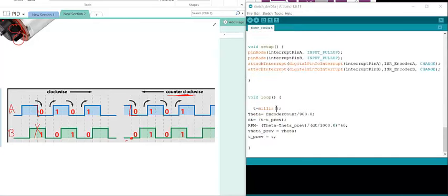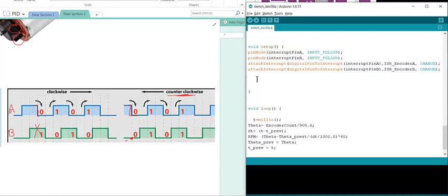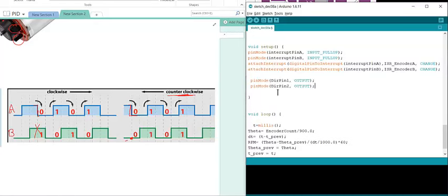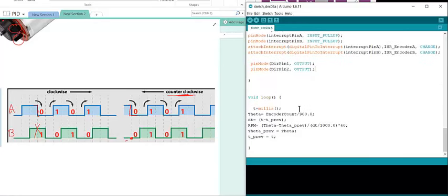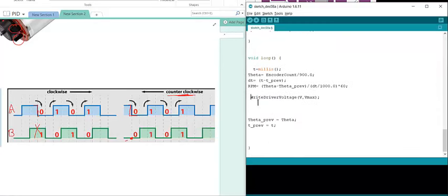Once we write the motor function, we have to set up our void setup function. So we'll set up the pins. We're saying these two pins are output. And we'll go to our main loop and basically say that voltage will be written. We'll just write voltage to our driver function to run the motor.